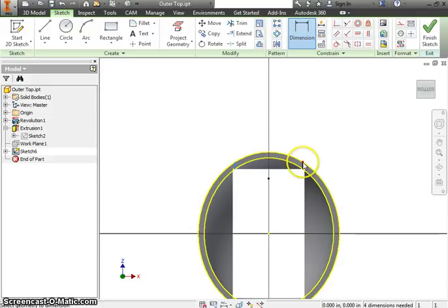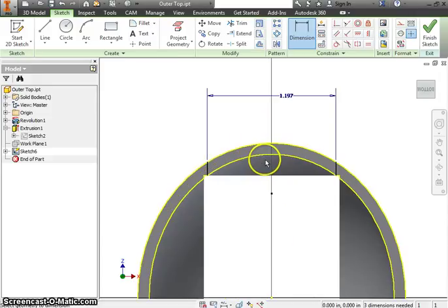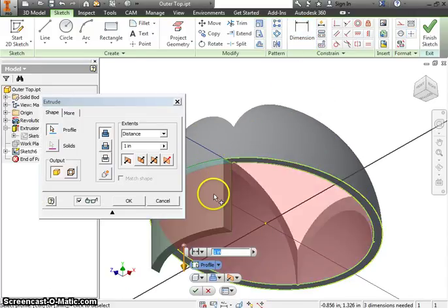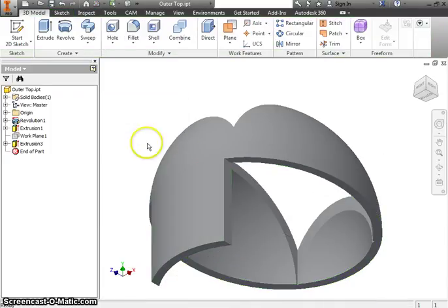Now I made sure that I had that lined up ahead of time, so that's the midpoint that I had before with the rectangle. So these lines are equally spaced out, and now when I go to extrude, I can just click on that little middle bit, and I'm also going to go down the 1.197. That's what the student originally had.